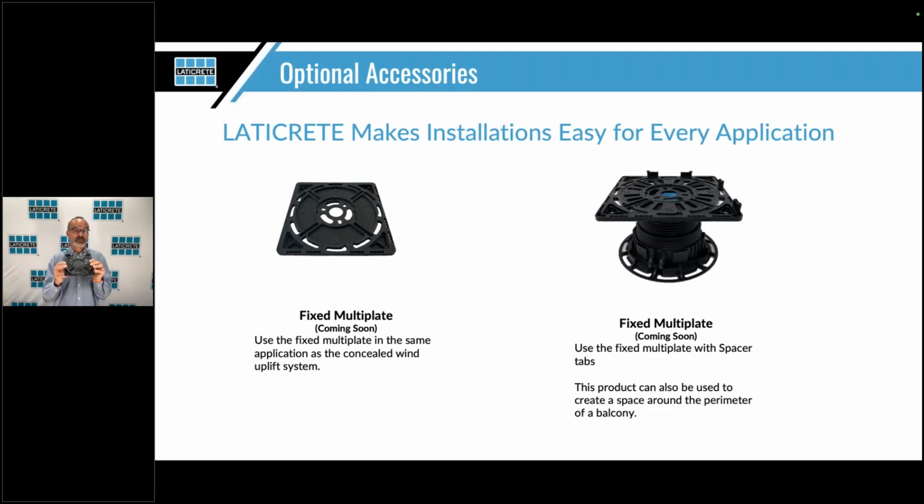Once that's installed, then it's much easier to use. Now, you can break the tabs off of the tab spacer. And what's nice is you can take the tabs and drop them into the sides, and what it's going to give you is your wall start. So I'm going to put these 4 in here just like it's going to be a corner. So now I've basically made a wall side, put it in there, and that will gap my stone away from it, giving it drainage. Very, very useful product. We should have it in the next month or so.